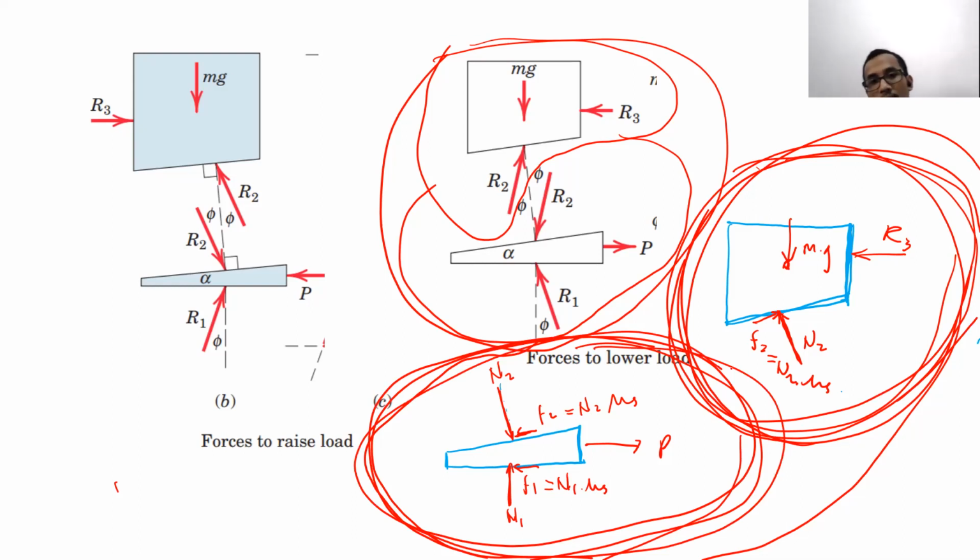What you mean is separating the free body diagram into two parts? No, not two parts. What I mean is, just now I explained several ways to draw the free body diagram of the wedge: you can join the normal force and friction force as R, or you can separate them. I suggest you separate the normal force and friction force, because by doing so you can see clearly what the components are.